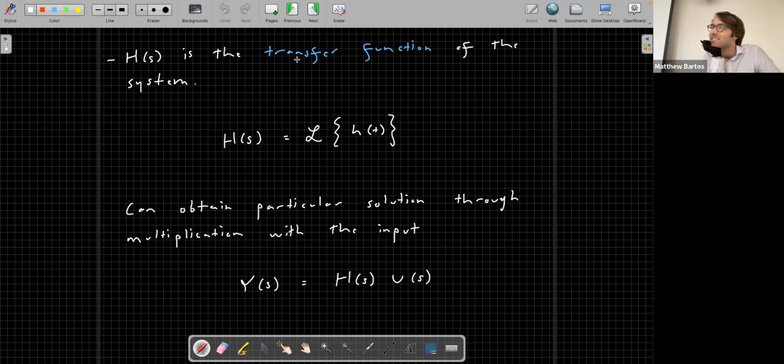You do the Laplace on the left-hand side of the derivatives, then you factor everything out, so it's all frequency coefficient. Yeah. So there's a simple one-sentence answer that might help you think about it a bit. The transfer function is the impulse response function in the frequency domain. So that's another way you can think of the transfer function of a system.